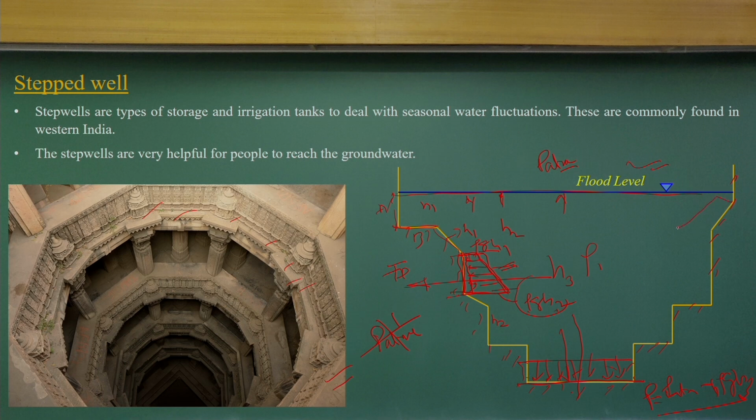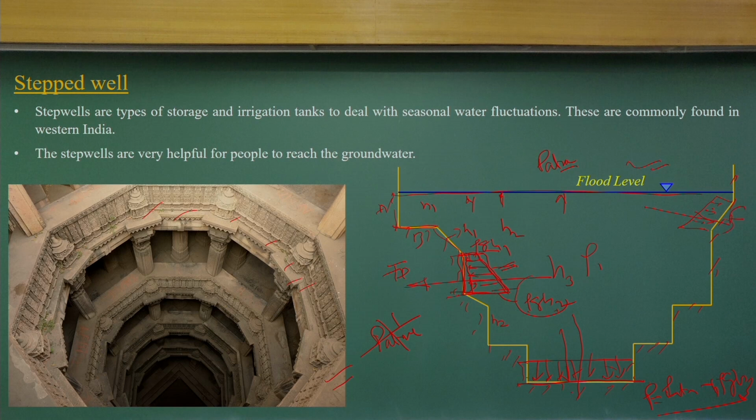The pressure will vary in a similar trapezoidal way, and the pressure will be normal to this inclined surface. For that pressure diagram you again find the area, or do the integration, to find the force acting due to the pressure distribution. Again you look at where the center of pressure is, the point at which this pressure force acts.